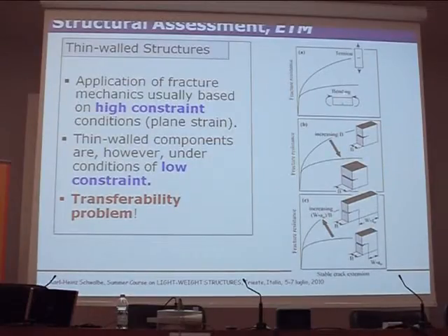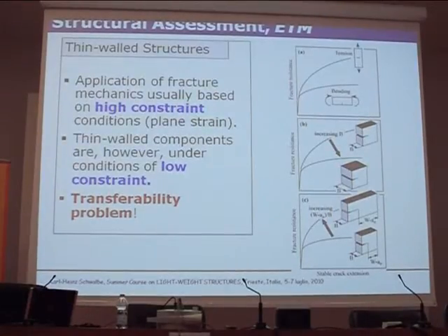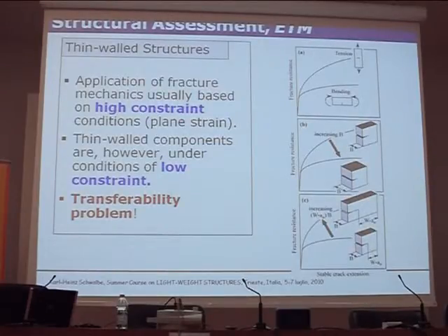Okay. Here, bending versus tension. Bending has higher constraint than tension. Here, increasing thickness leads to higher constraint. And constraint is decreased when we keep thickness constant, but we extend the ligament here. And this is something, by the way, that we found in our experiments. And so it's kind of a mess here. You know, you had to vary so many parameters. And so, like I said on Monday morning, an elegant solution is using numerical damage mechanics models. Now I'm checking the time again. Sorry for that.